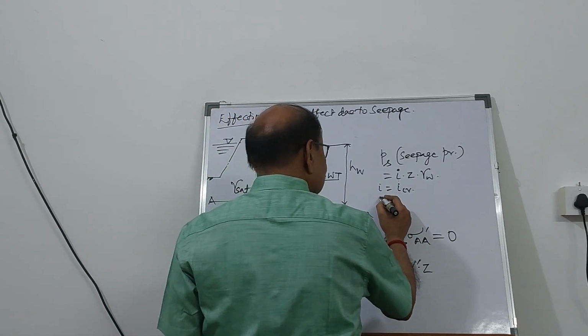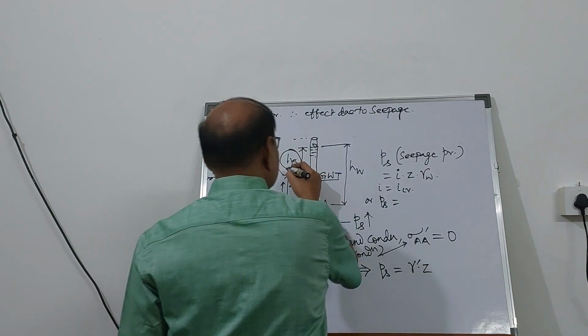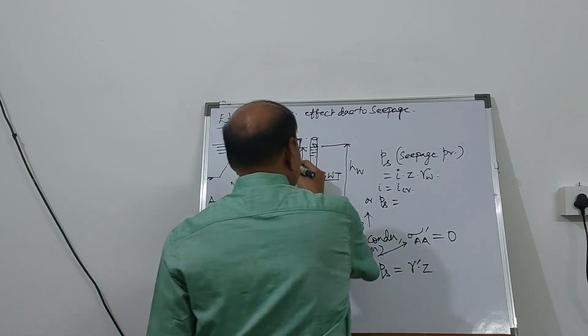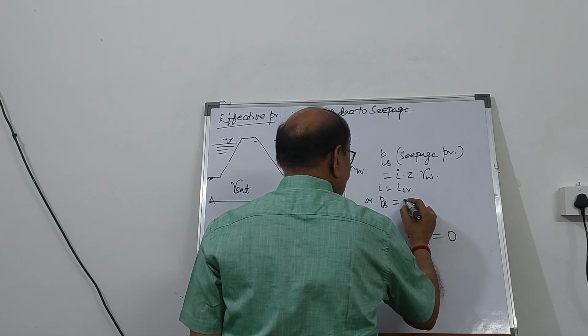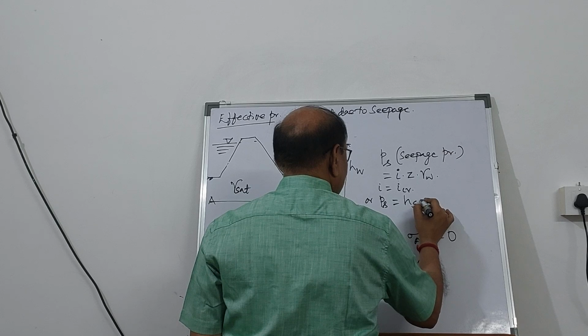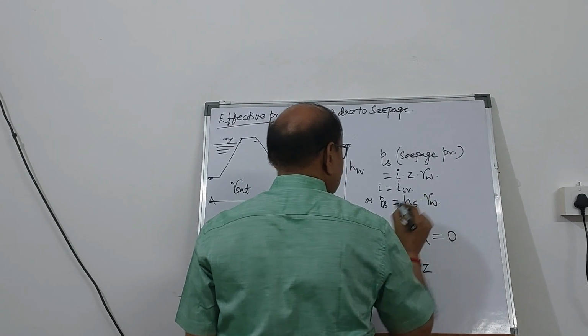Or we can say the seepage pressure is the net head that is causing the seepage, multiplied by unit weight of water.